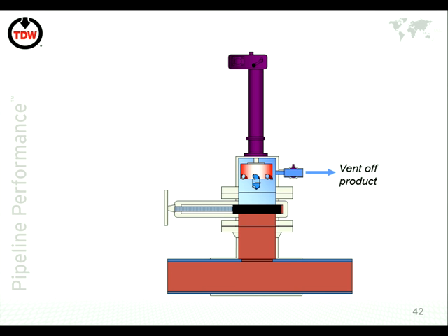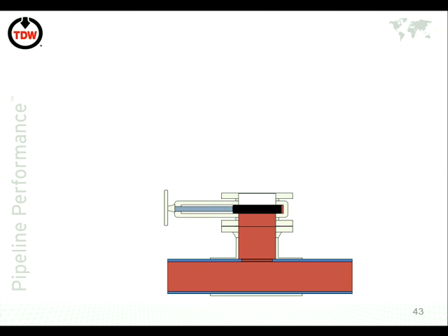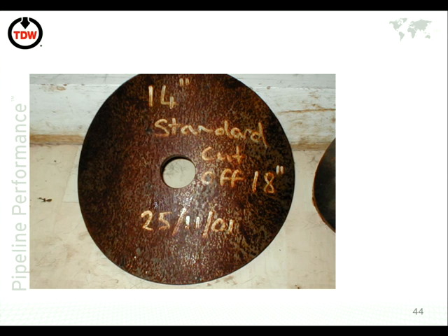But most of the time, the reason you do a hot tap is because you want to do something else with it. And I'll come on to that in a minute. So every coupon which comes out is marked up, it's taken away, and engineers will have a look at that, and they'll gather a little bit of information. Might not tell them anything. I mean, in an ideal world, there'll be no marks on the inside. It will still have the coating, and that will give them an indication that the integrity of the pipeline is still good. But they will match it up with ILI data.